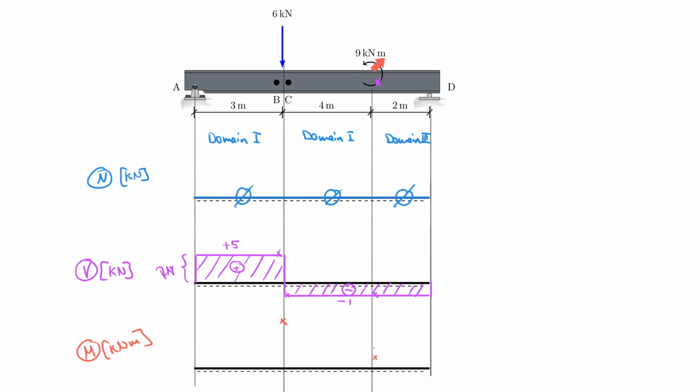In fact, you will find that then you have the 9 rotating counterclockwise and therefore going against the moment that comes from your internal force definition that is located on your little study card. So therefore, you will actually find that this bumps up the value by 9. So really what I will end up with is with another cross right up here. And remember that this value here was plus 2. And then we have plus 9. So this is plus 11. And that makes perfect sense. And you will see this when I draw the diagram.